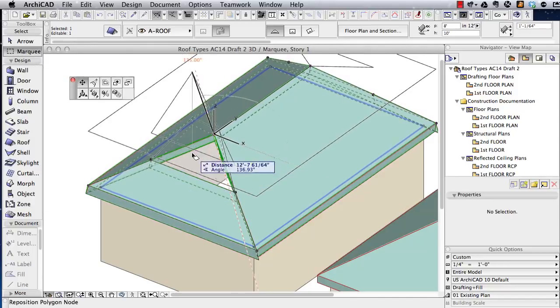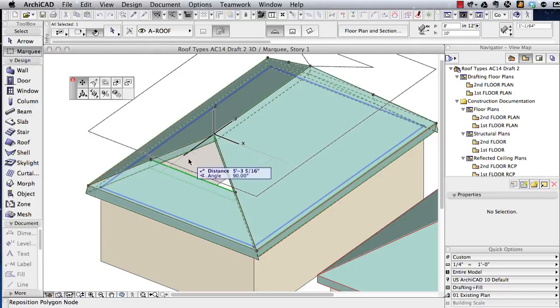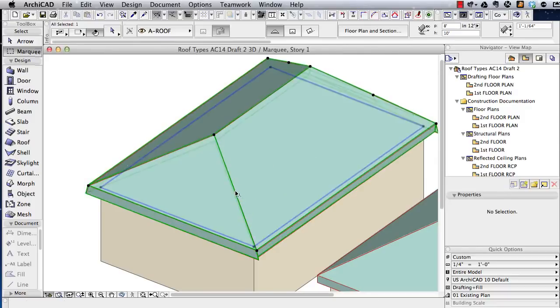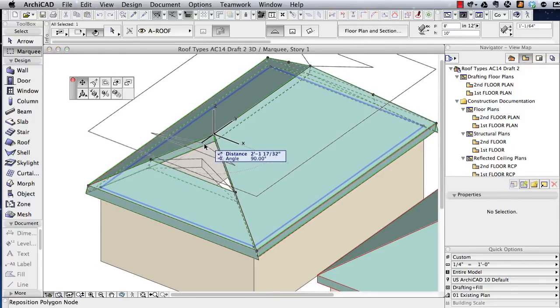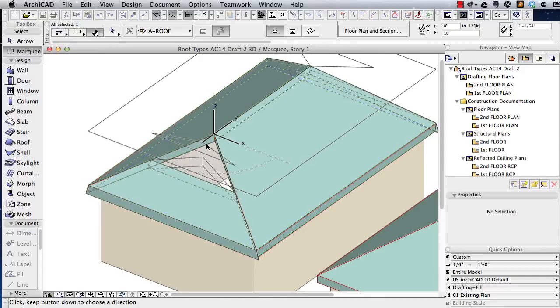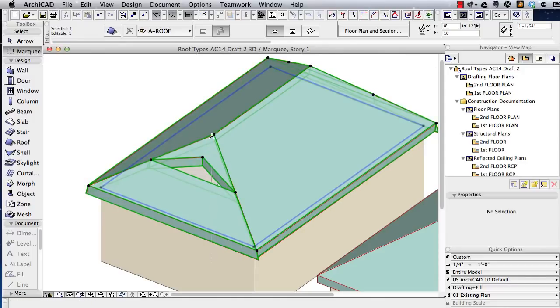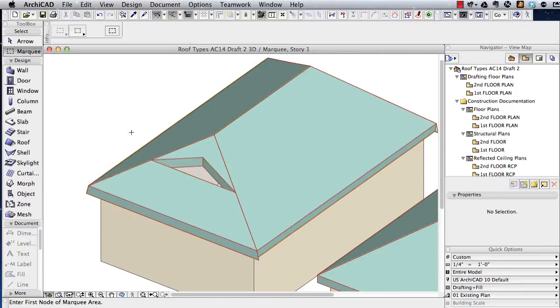Now if I use the Shift key, trying to lock it in a row here, and try to take this out, say, in line with that point, you notice that this hole disappears. It turns out that if I bring this, and I just use the Shift key just to illustrate it, just bring it part way, you'll see that although it looks like I'm repositioning what might be the upper pieces over, it actually is creating more of the bottom piece, essentially removing part or all of that hole.